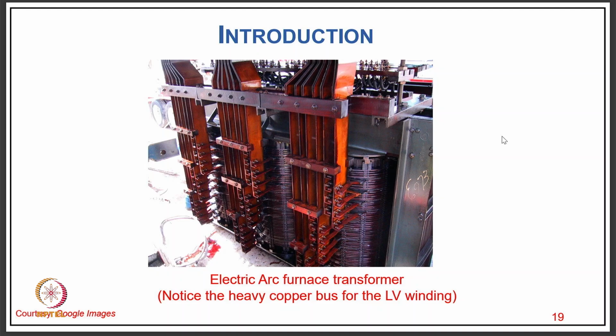or even lower than that, such a large single-phase load we cannot connect directly to the three-phase supply system. So we have a special arrangement of these furnace transformers for this purpose. The purpose of those transformers is, number one, isolation, and number two, to convert the supply from three-phase to single-phase. But when both the furnaces have almost equal load, they behave as a balanced load on the three-phase supply system through this transformer arrangement.